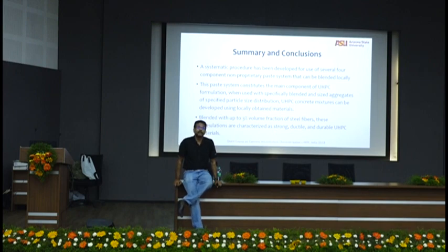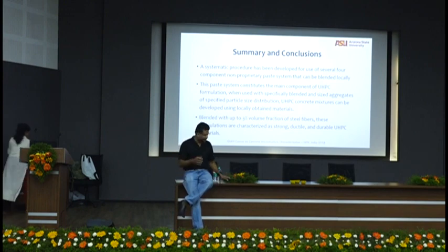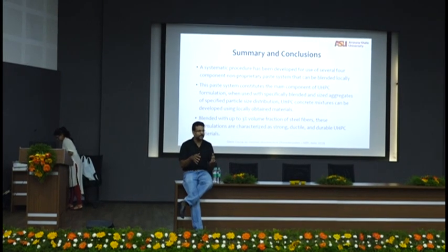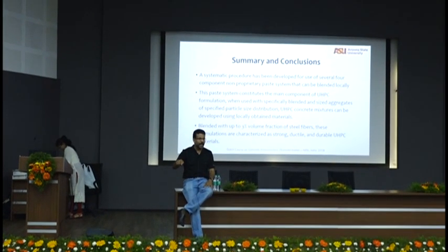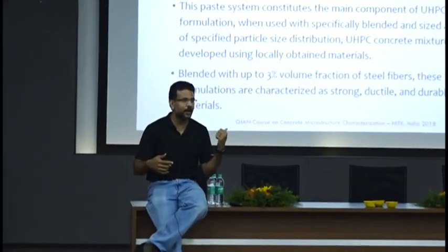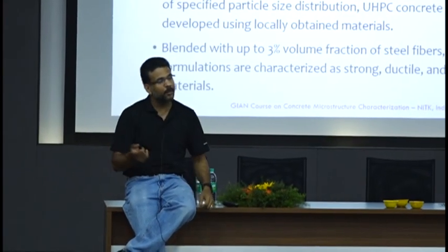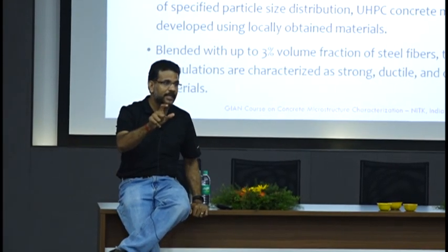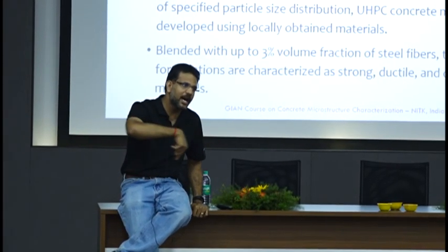Well, at the end of the day, it's not just the speed of mixing. It's a combination of speed and time. And the speed of the mixer also is a function of, if you really have a mixer that has speed control. Normally all the mixers that we have are not speed controlled. Our mixers, we put the material in, you have a medium, high, low, and even if you put in high, for a mix that is so dense like this with little water, it will mix only very slow. So what you want is a mixer that will have power control in the motor, that will give additional power to get you the RPM that you want.